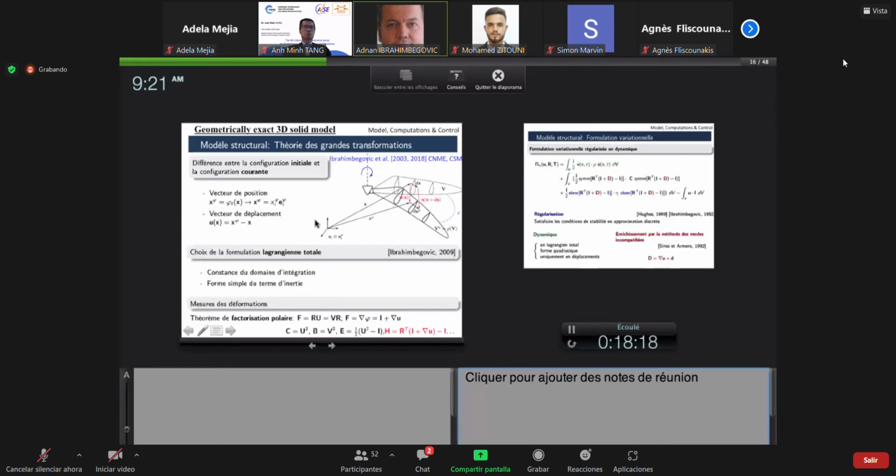So let me go to 3D modeling. You should do the same thing, only we allow for the case that the wind turbine blade can have a very optimized form, which is not easy to represent by a single beam model. So we represented it with 3D solids, where here is the initial configuration and the deformed configuration. And the key point is what strain measure to introduce to monitor this type of deformation.